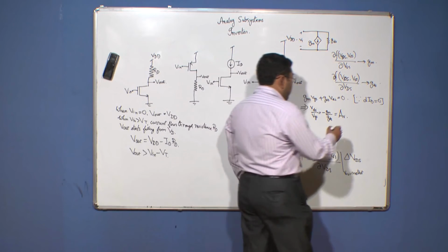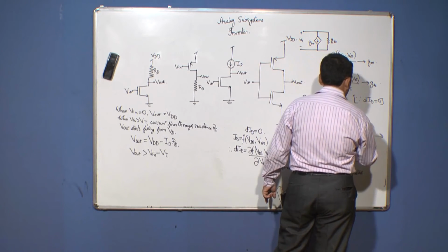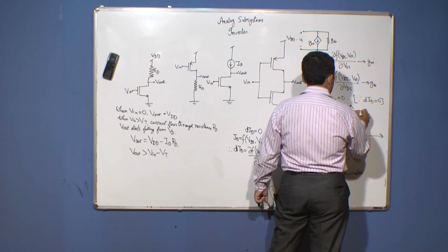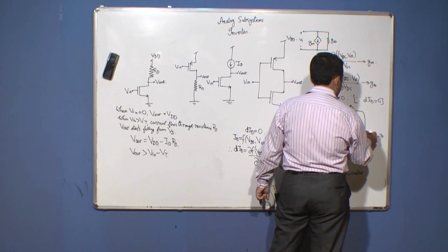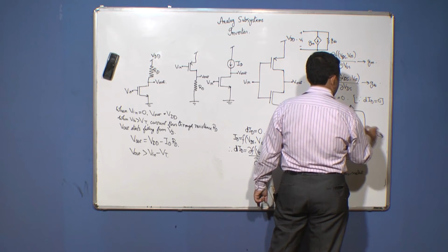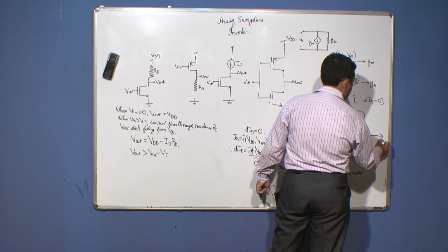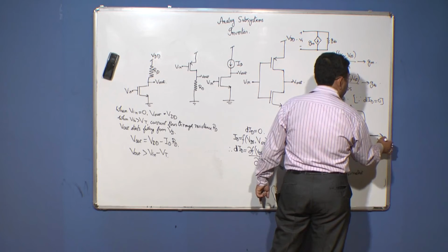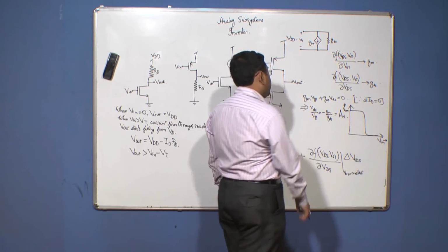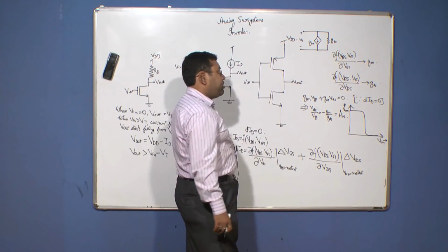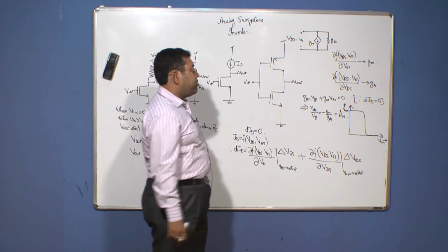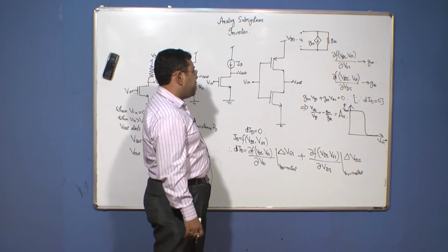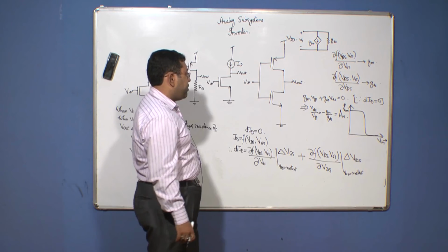So in essence, the output characteristics of the NMOS and PMOS transistors connected as a push-pull inverter becomes something like this. In fact, this is the inverting amplifier that gives the best possible response amongst all the different types of inverting amplifiers studied so far.